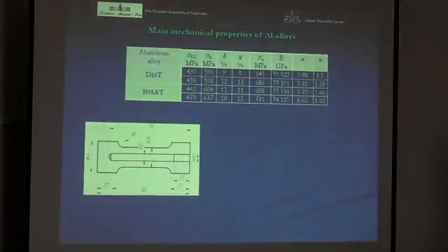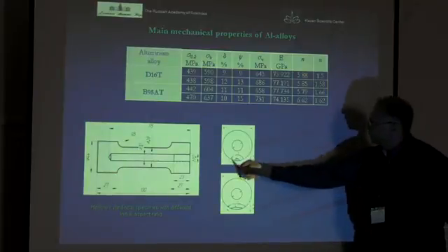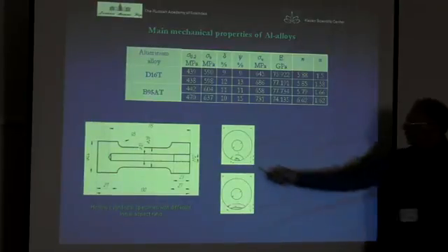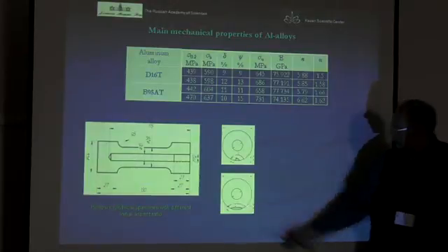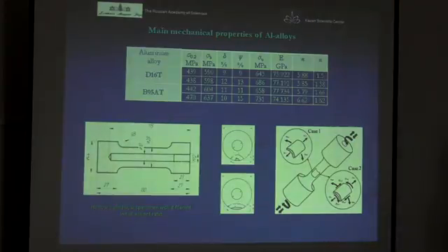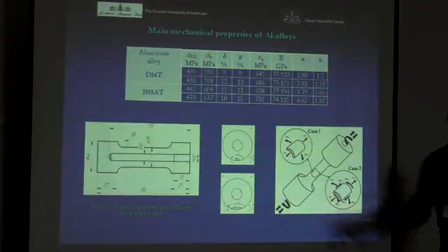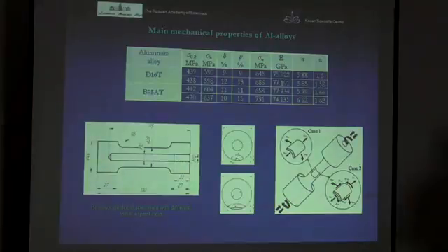We tested hollow specimens with wall thickness 10 millimeters, with initial surface flaws with different aspect ratios. One of them is aspect ratio equal to 1, another one is 0.3. Loading conditions are, first case, cyclic tension; another one, combined loading: cyclic tension and cyclic torsion in phase loading.